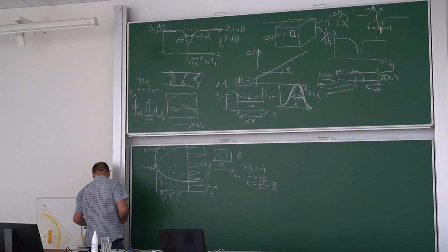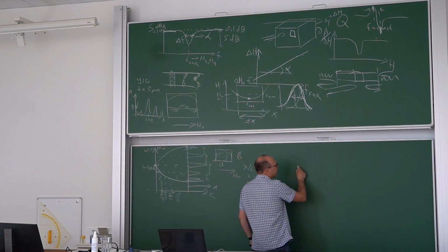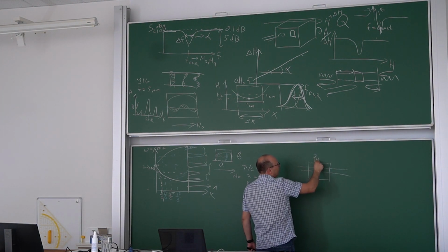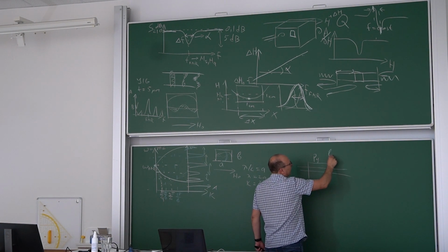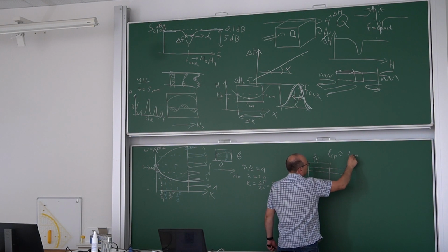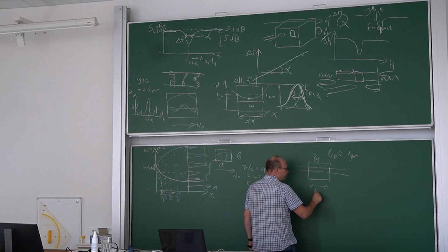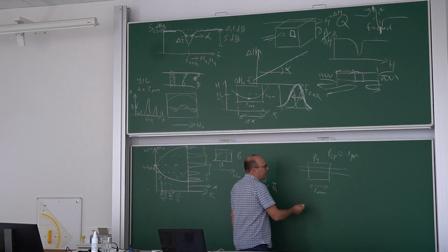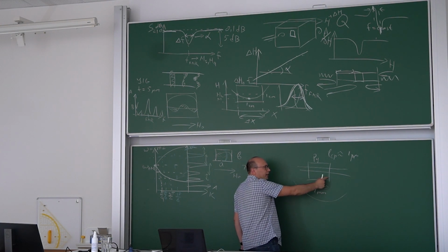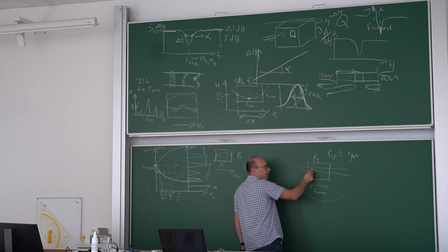But if you have another situation, like for example, this is your antenna, this is your big permalloy sample, permalloy because the propagation length will be of the order of 1 micrometer, and you have a 1 millimeter long sample, and then you put it in a strongly non-uniform field. Of course, there will be no eigenmode, no single mode across all this, because everything that is excited here propagates only 1 micron.